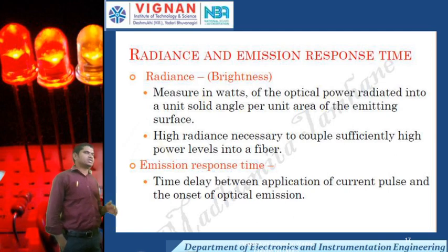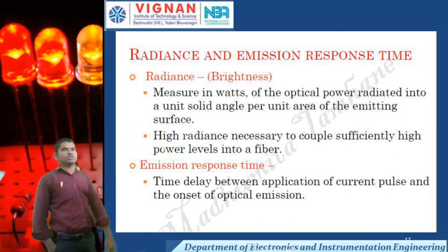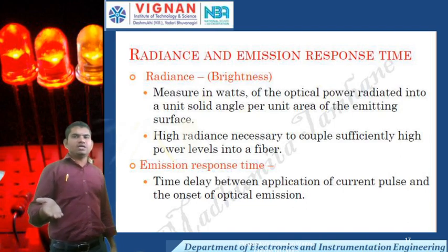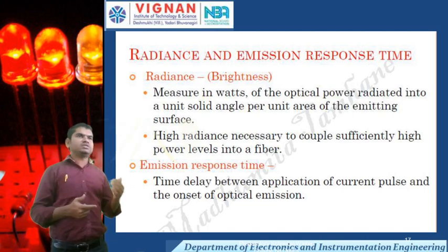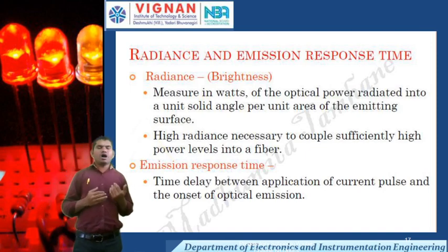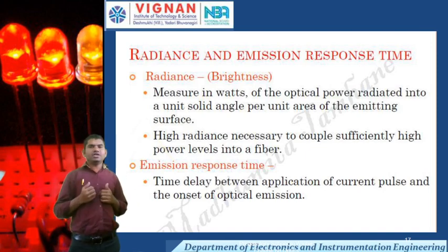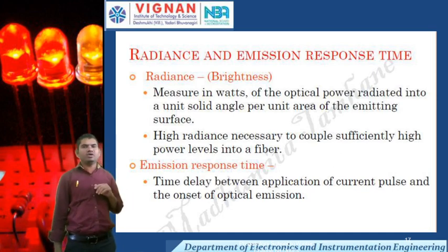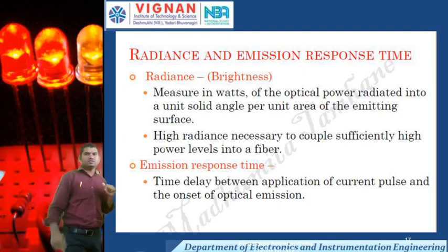Now radiance and emission response time. Radiance means the brightness. It is measured in watts of optical power radiated into a unit solid angle per unit area of the emitter surface. High radiance is necessary to couple a sufficiently high power level into a fiber. This is radiance.